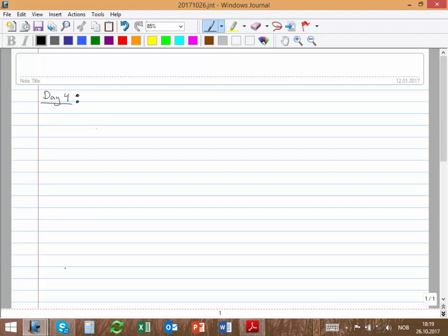Usually, no pipeline is completely horizontal. You have some inclination. But the thing is that for gas, really the hydrostatic is very, very small. So it's a good approximation to use a horizontal pipe for many of these flow lines. Unless you have, of course, maybe 300 meters going up and down. But if you have, for example, changes of 1 meter in elevation, you can really neglect it because the main pressure drop comes due to friction. So that's why I think it's important to discuss a bit what happens with a pipe.